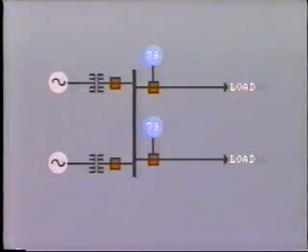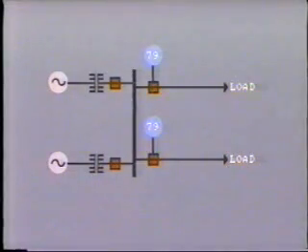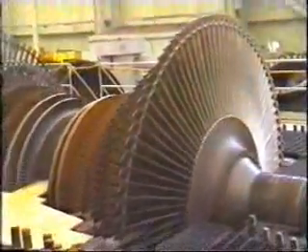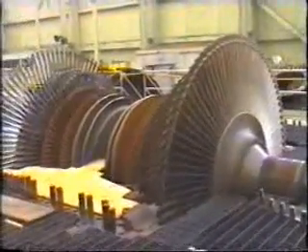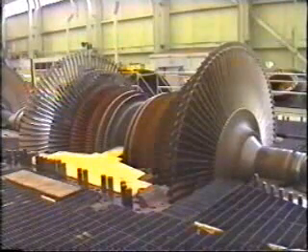This is where the transmission line is located close to one or more large generators. The shock to the generator of suddenly rejecting load, then applying load again, could conceivably cause mechanical stress and ultimate damage to the turbine and generator rotors. For these reasons, and to preserve system stability, instantaneous reclosing relays are usually not installed at locations close to a generator. We can see that the application of reclosing relays depends upon the system location and the specific system.